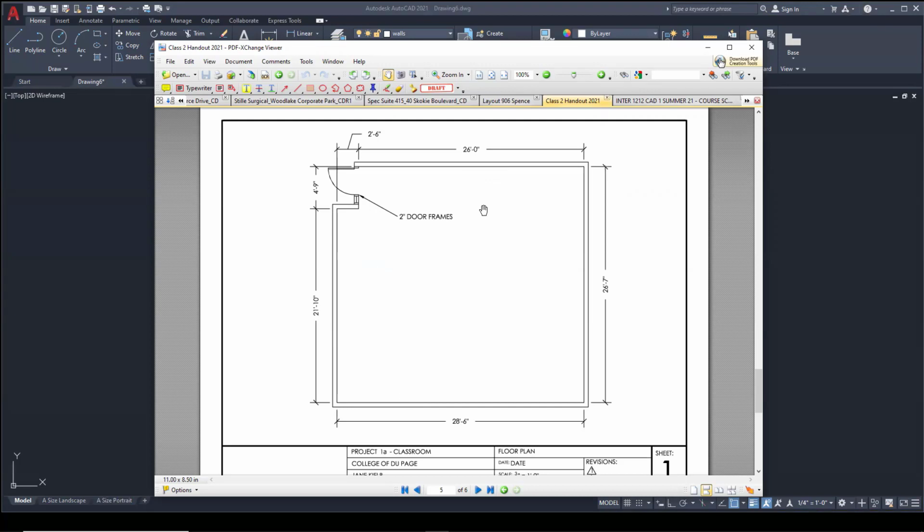So this is a classroom and it's got some walls here. The door here is set in. So I would assume that over here on the left, running vertically, is a corridor of some sort, right? And you're walking down the corridor and then you go into the classroom. And the door is recessed into the room a little bit so that when the door swings open, it doesn't encroach into the corridor any more than 7 inches. That's why this doorway is set into the room.